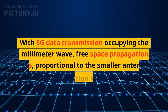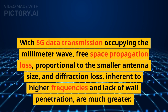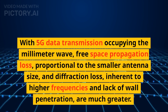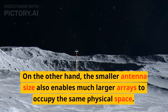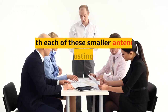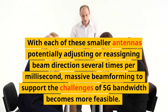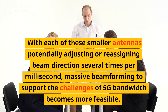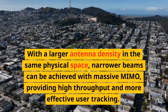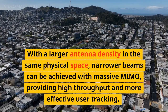With 5G data transmission occupying the millimeter wave, free space propagation loss, proportional to the smaller antenna size, and diffraction loss, inherent to higher frequencies and lack of wall penetration, are much greater. On the other hand, the smaller antenna size also enables much larger arrays to occupy the same physical space. With each of these smaller antennas potentially adjusting or reassigning beam direction several times per millisecond, massive beamforming to support the challenges of 5G bandwidth becomes more feasible. With a larger antenna density in the same physical space, narrower beams can be achieved with massive MIMO, providing high throughput and more effective user tracking.